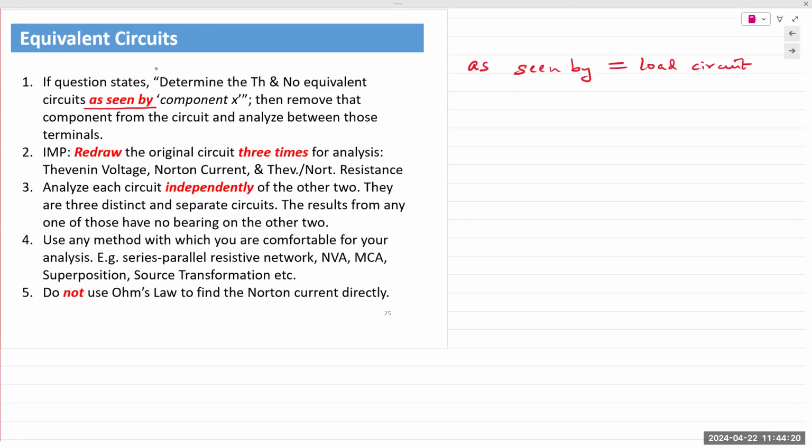Make sense? If you look at any speaker specification, it will always state the impedance in ohms, either 6 or 4 or 8. So the output for any audio video receiver that you connect to your speaker systems will always have an output rating stated in ohms. If you have easy access to the back of your audio video receivers, you can take a look, or you can download any manual for any brand and it will state in the specifications what the output impedance is. The reason is we want it to match the next succeeding stage. And that would be the Thevenin resistance of the preceding circuit.